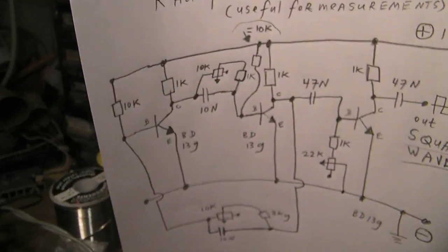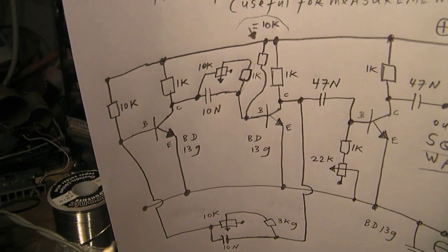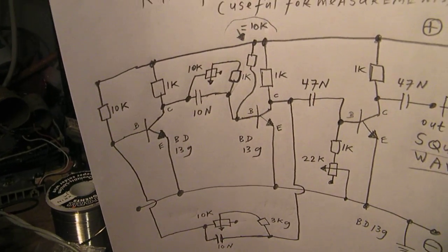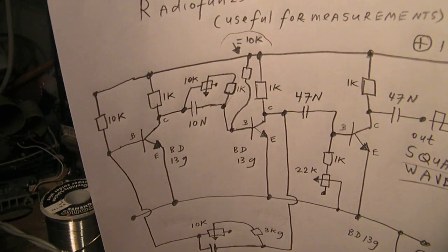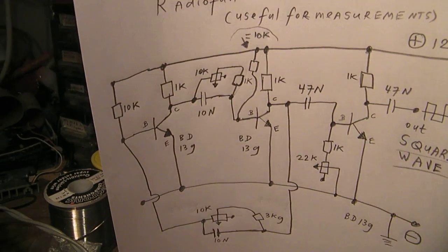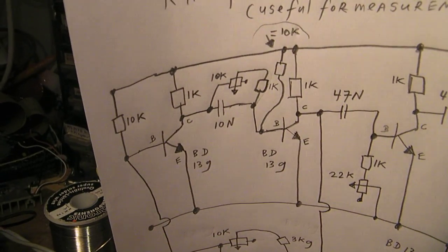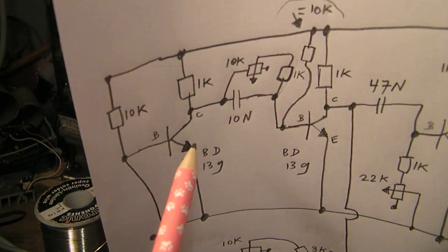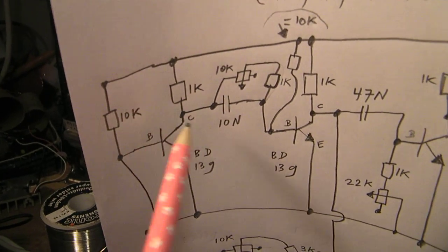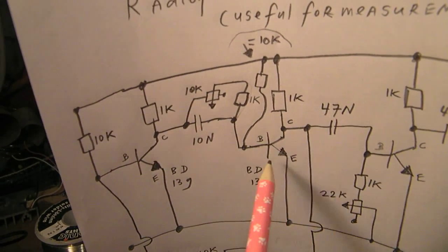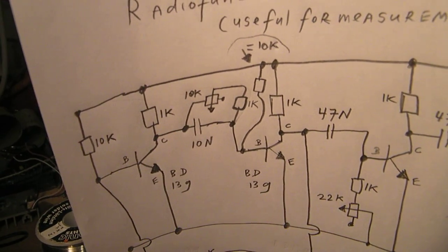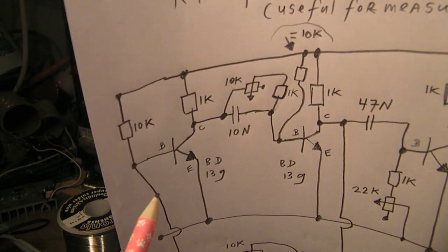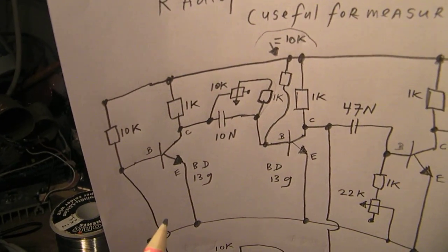And the astable multivibrator circuit can be made with tubes, triode tubes, and also with transistors. And the properties are very simple. An element here and here that's active, it amplifies, could be a tube, could also be a transistor, in this case a transistor.